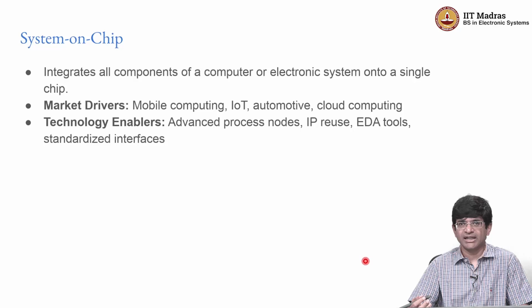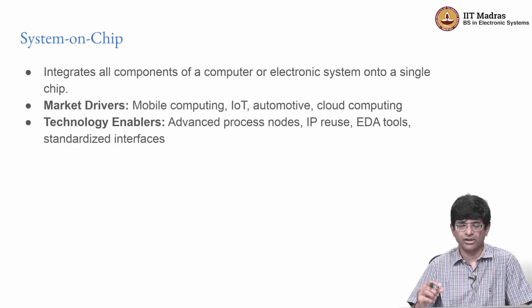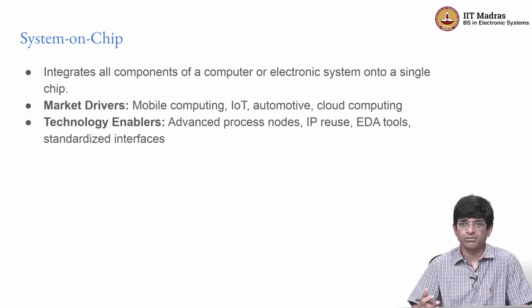What that means is that you typically have what looks like a chip, but it's not one single silicon wafer, or rather a single silicon die. The die, by the way, is the specific unit of the silicon wafer that is cut out and has all the circuitry that you need. So, modern systems typically tend to be system in package, which means that you have a package with appropriate input output pins, but which may contain separate pieces of silicon that are all integrated together on some kind of common substrate. It differs a little bit from a system on chip, but it also shares a lot of similarities. So, for practical purposes, right now we are not really going to differentiate between them.